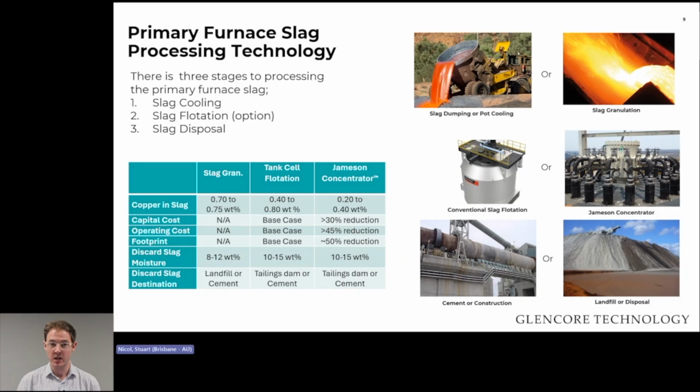So there are different destinations in what you do, and you mix and match. Generally, if you do flotation, you'll produce a slag tailings, which we need to be careful of. You either landfill or dispose of it. Some sites have used slag flotation tailings in cement production as well. But there's mixing and matching and some choices here as well. A lot of it comes down to the level of recoveries you wish to achieve, as well as the final destinations of that slag and the trade-offs and options there.